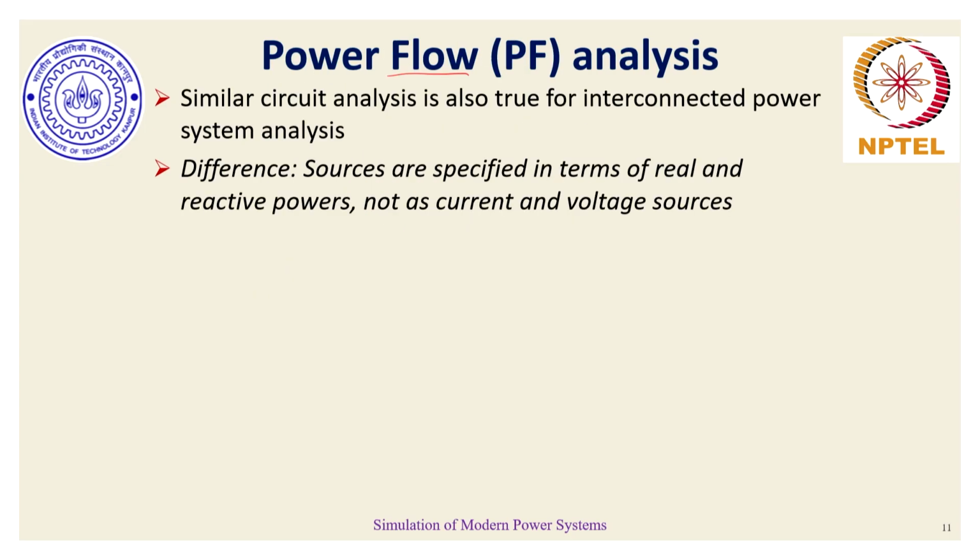In practice, in reality, for any generator, transformer, or load we take, be it the light load that we have in this room, if we check its nameplate rating, the first rating that often comes is the power that it is going to consume, and the voltage at which it is supposed to operate. From there you can find the corresponding current at which it will operate.